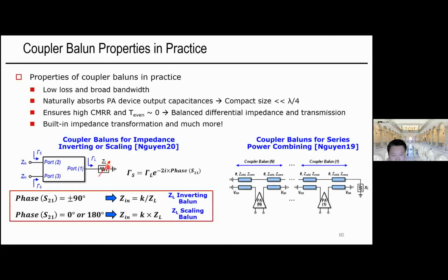Thank you for the question. First of all, I think it's common practice that we want to separate the supply voltage for the driver and the PA. At least we want to ensure a very good bypass between the two. This is really for the preservation of stability, because we don't want any feedthrough and feedback through the supply lines. That's the main consideration. However, as I know, in many product level designs, sometimes having separate supply lines is not feasible. Then in that case, you need to carefully model the supply lines and the bypass. That's important.